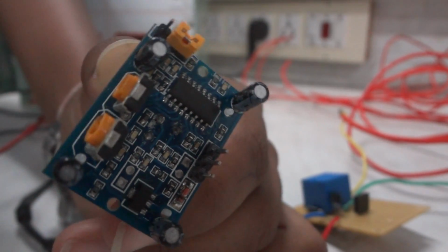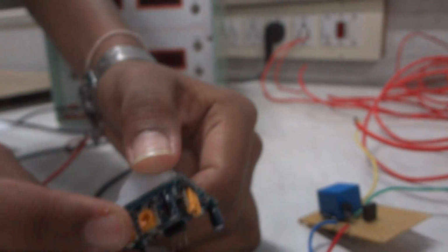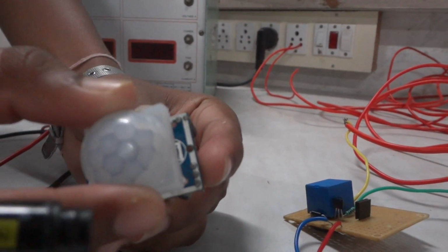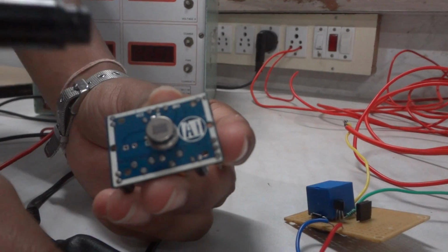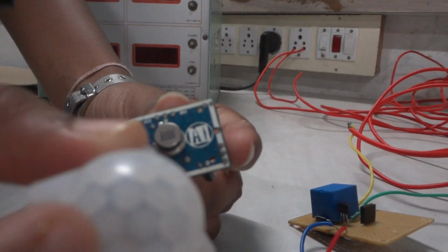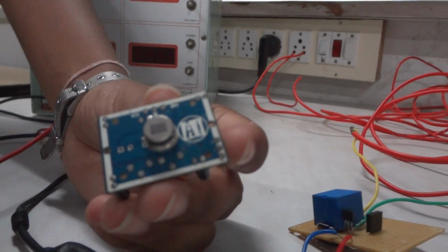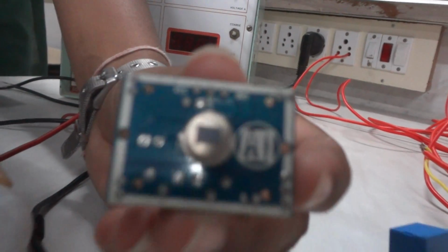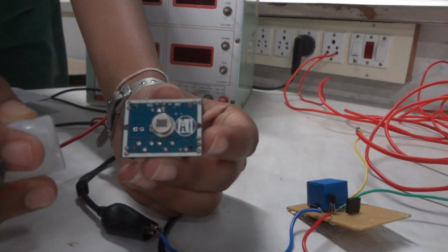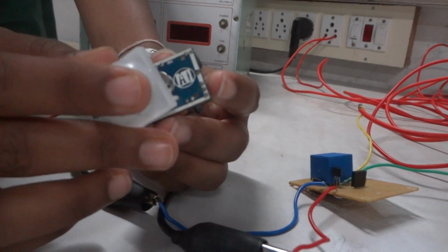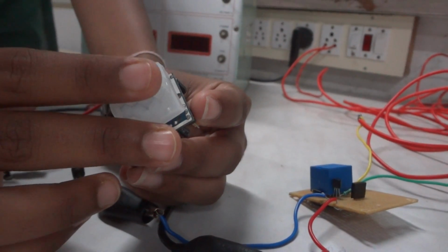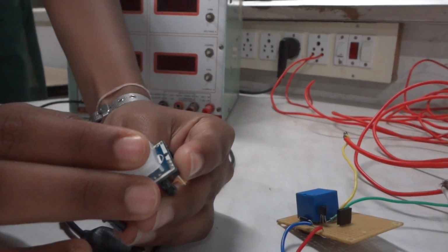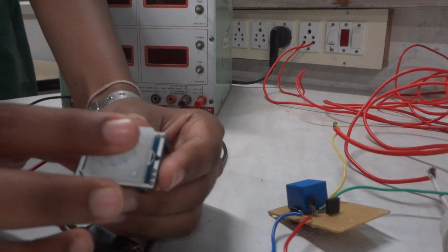The pyroelectric sensor is covered by a plastic cap which is called a Fresnel lens. It is used to focus the infrared on the inner material. It has a wide range of almost 180 degrees. PIR takes some time to stabilize itself according to surrounding conditions, so you can turn on the bulb after about 10 to 60 seconds.